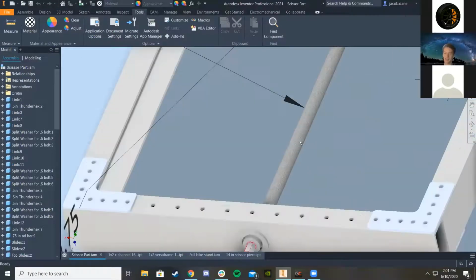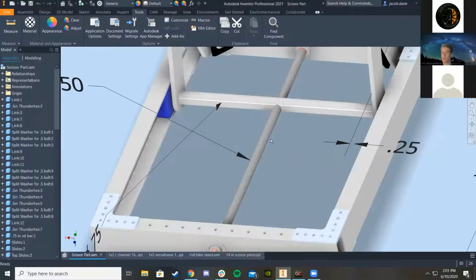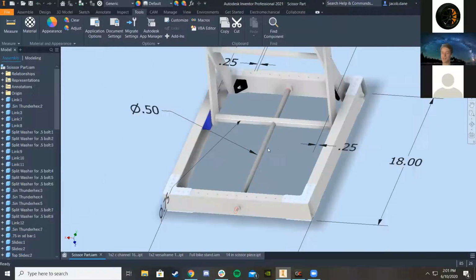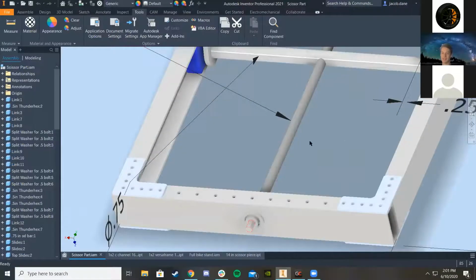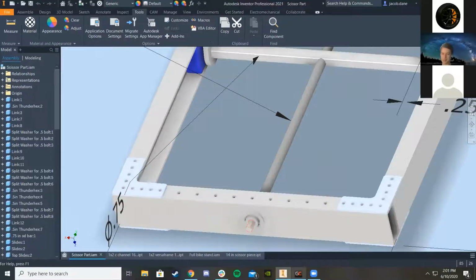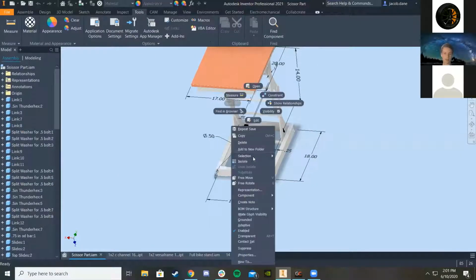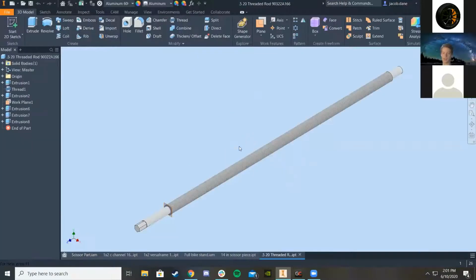Actually, yeah. So this is the screw part. If you want, on McMaster-Carr, I've already looked at the dimensions of what we want for this. And for that part on McMaster-Carr, they actually do have it available for you to download. But the problem with that is when you have an actual screw and bolt mechanism, it can sort of make the constraints really weird, especially because it has a lot of weird threading that goes along through it. And so I'm just going to make a cylinder, and then Autodesk has a way that you can just add an image of threads so that you're still acknowledging that they exist, but it makes it a lot easier. And so I will show you here. I want to see how long this file is first.